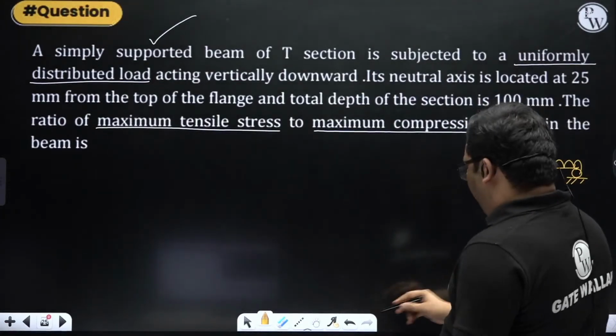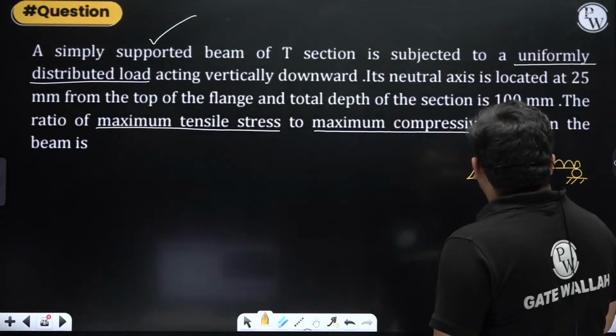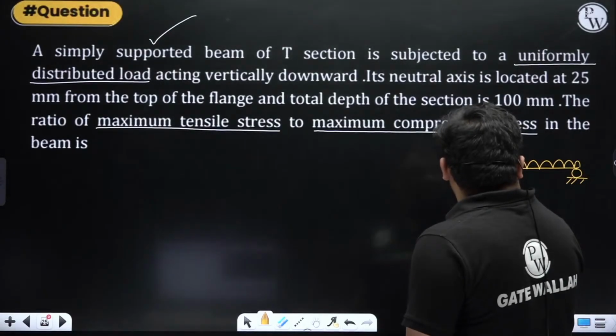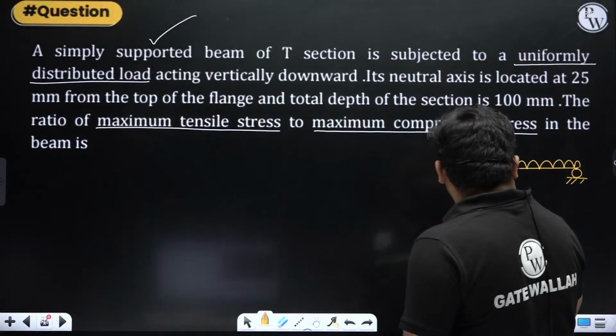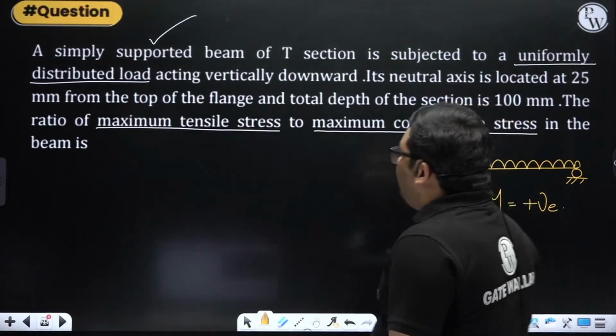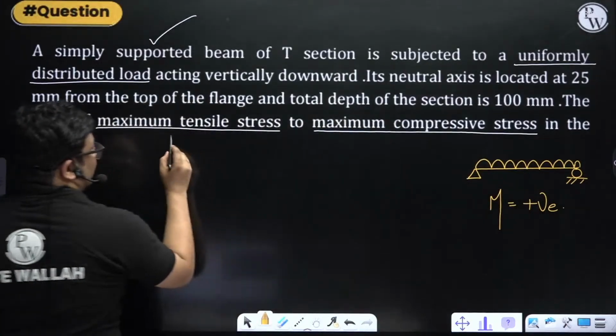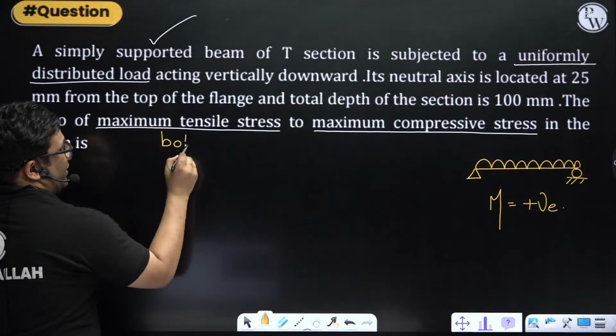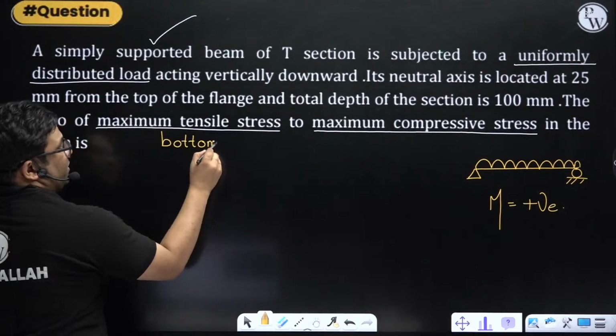So if the bending moment is positive, then we get the maximum tensile stress where? We get it at the bottom, na? Yes, for positive bending moment.